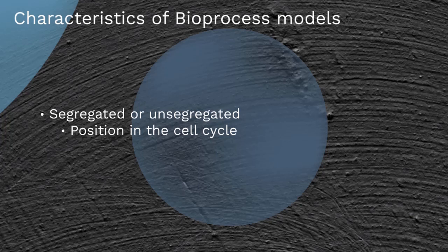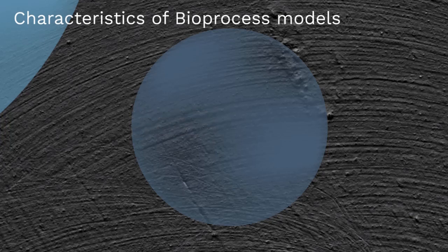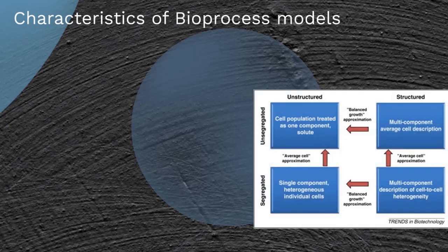The choice among these properties depends on the objective of the model, and such reaction rates vary with time and are usually influenced by many parameters such as substrate, biomass and product concentration, and also the physicochemical conditions such as pH, temperature, dissolved oxygen concentration and the concentration of various growth inhibitors.